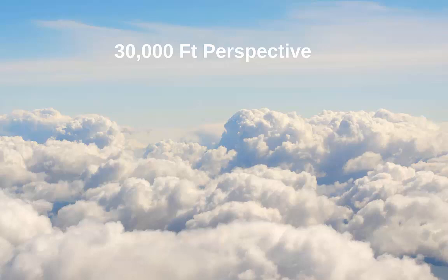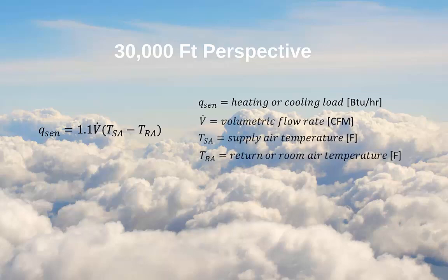Let's review how we bring heat to and from an occupied space. The amount of sensible heat being brought into or out of a space follows this simple equation. As we have talked about before, the room air temperature is typically the control variable. That means that is the variable we want to keep at a certain set point. As the heating and cooling requirements of the space, represented by Q sensible on the left side of the equation here,